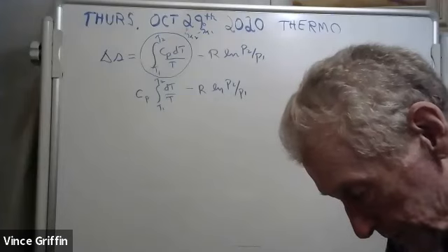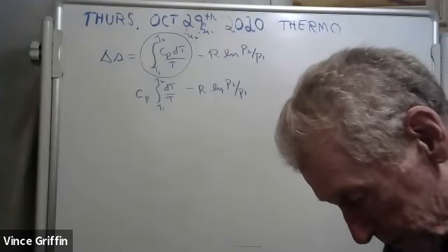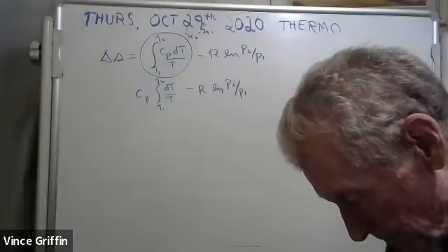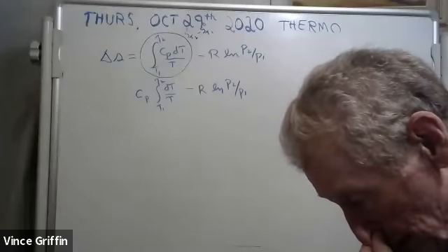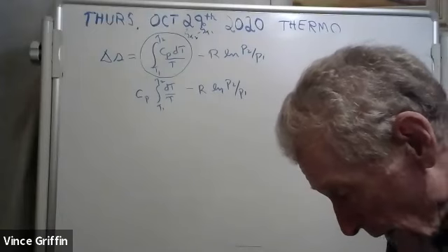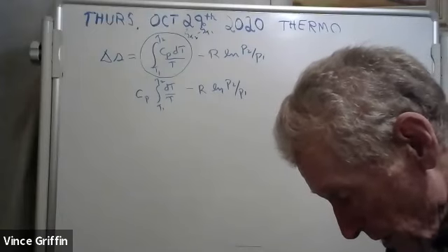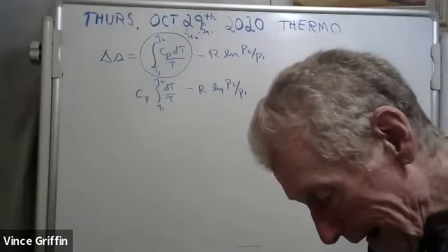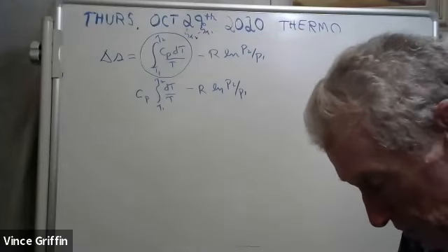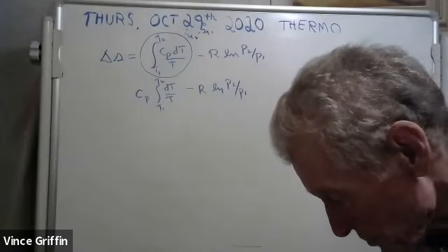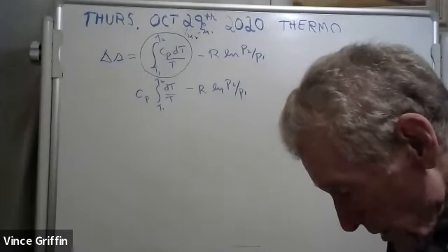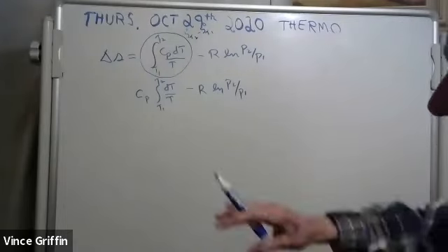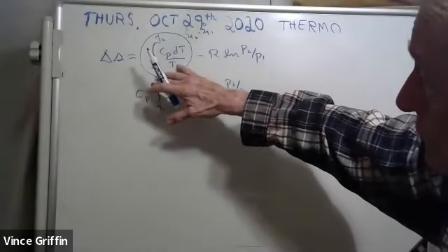Trying to find some here. Yeah, I see some on table A11. There's some S0 with a little t underneath it there. Those are called ideal gas integrals. And there's a whole bunch more. There's some on table A13, A14, A15, etc. They've integrated those for you.